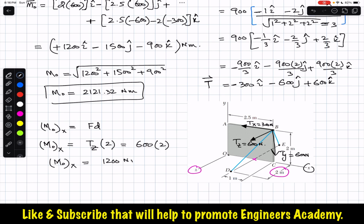and this is equal to 1200 Newton meter. And as I have told you, this is going to rotate this wall in the counterclockwise direction about the x-axis. So the moment is in this direction. If we curl our right hand fingers, the thumb will point out in the positive x direction, and this is the counterclockwise moment. So we can say that this is plus, or counterclockwise. So the moment about the x-axis has magnitude 1200 Newton meter, and it is in the counterclockwise direction, or this is positive.